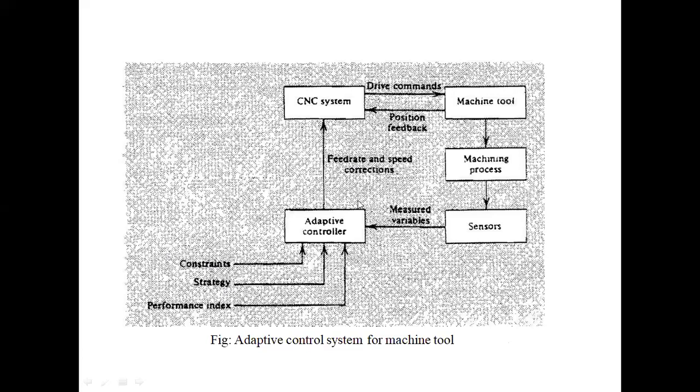For example, if the temperature was getting too high, you will decrease the speed and feed rate so that the temperature can come down. As soon as the sensors sense that, because of the decrease of feed rate, the temperature is getting normal, that feed rate will continue. As and when the part geometry is changing, as and when the tool position is changing, you have different situations, right?